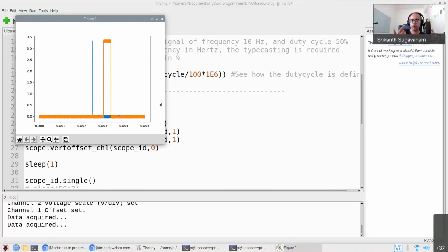So I already mentioned one problem or one limitation with the Raspberry Pi. The limitation is that the Raspberry Pi can accept only digital inputs. So you can work with analog sensors, but you have to put a chip in between, which is called an analog to digital converter, and then you can communicate with the Raspberry Pi.